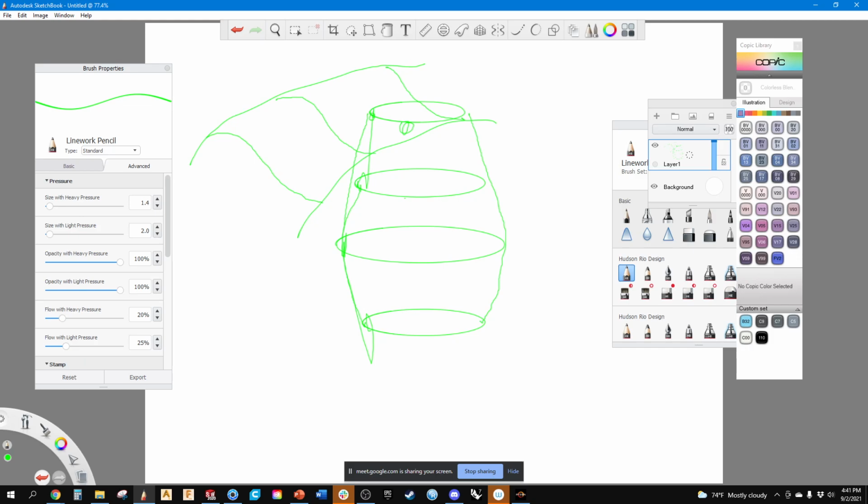So when I'm doing concept sketching, it may be a beautiful sketch. When it comes time to model it, I'll actually do an overtop and I'll draw in all my contour lines so I can get a better understanding of the form that I'm trying to create. And that gives me a plan of what my surfaces and my sketches are going to look like in SolidWorks.